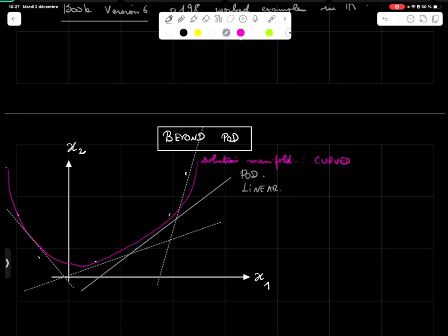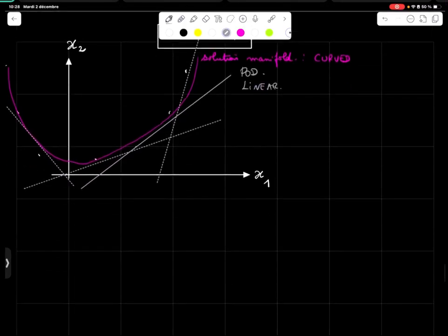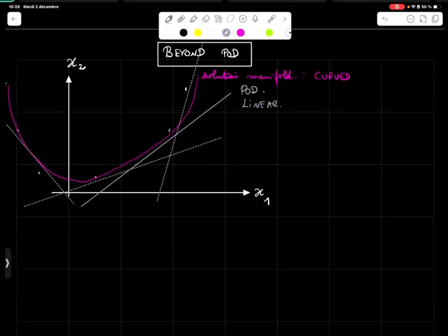Geometry, boundary conditions, parameters, and so on that we talked about. And for a nonlinear PDE, the solution manifold is even more nonlinear. So if you use POD or PCA, you approximate the manifold only locally, and for strong nonlinearities, you can forget it, and you will need some nonlinear approximation space. Okay? I'm not saying more about this, but you can imagine that there are several ways that you can deal with that problem.